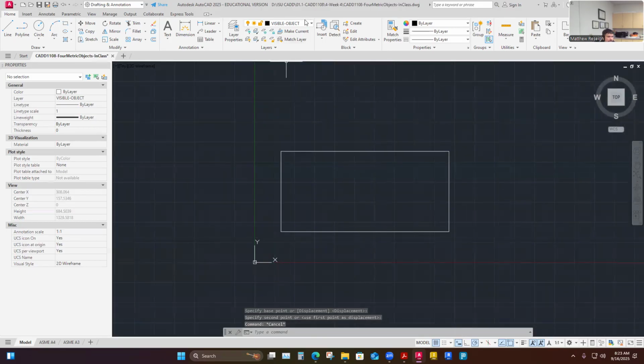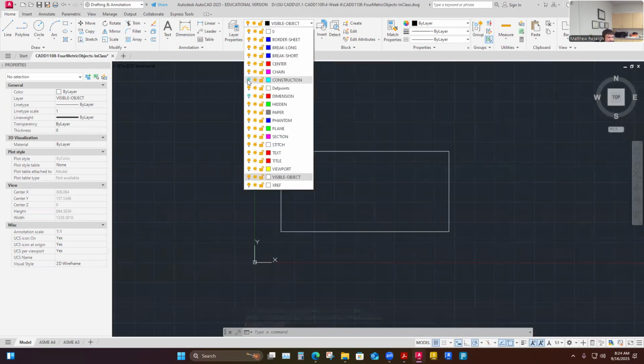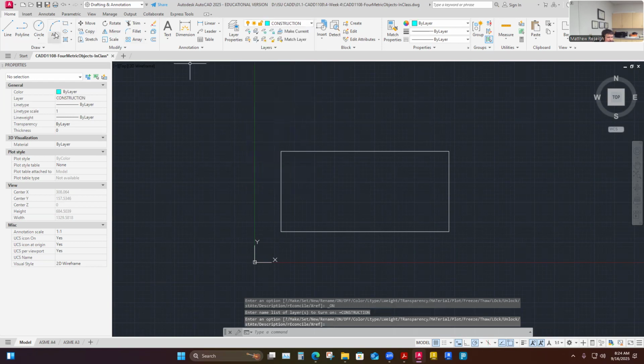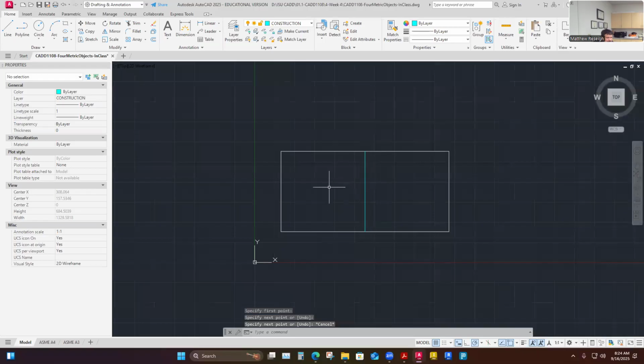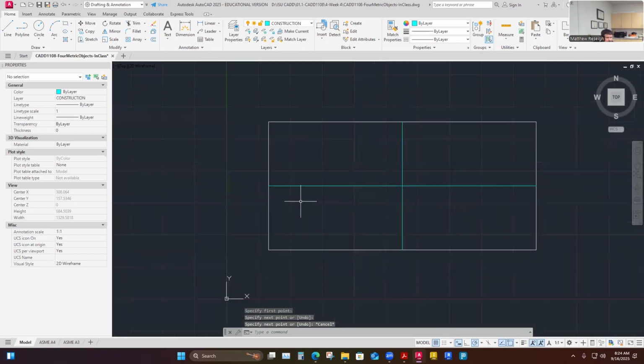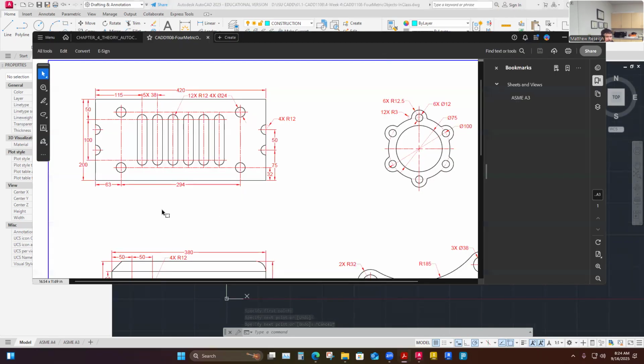Yeah, it can be helpful to have center lines on stuff like this. So I might turn on my construction layer. Center lines are pretty easy to snap if you have that midpoint grip on, that triangular grip point. I'm going to end up mirroring some stuff across this. Not that I need that line to show it, but maybe it's just a visual for me. I don't know if anything's technically measured off center. I don't think it is, but sometimes you will get a lot of dimensions pulling off maybe a center point, and in that case, it's helpful to have those. I don't really have any dimensions pulling from a center point, but I just put them in anyway.